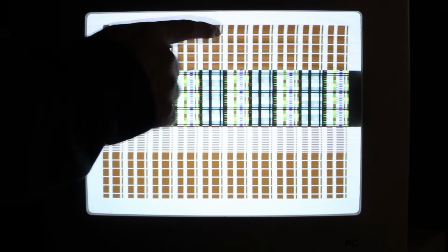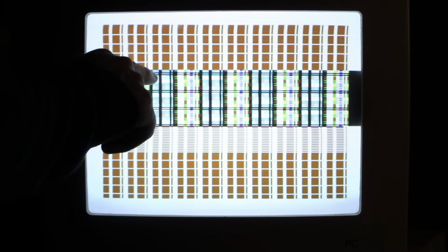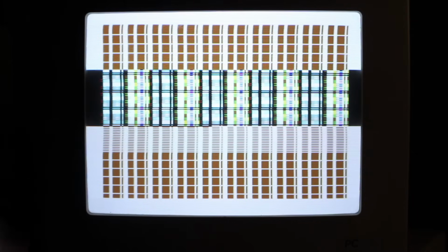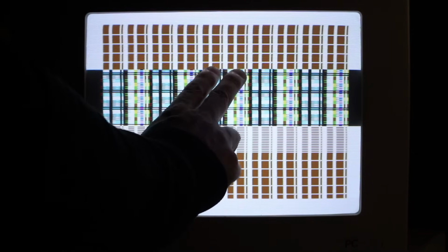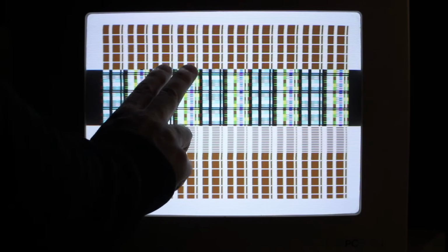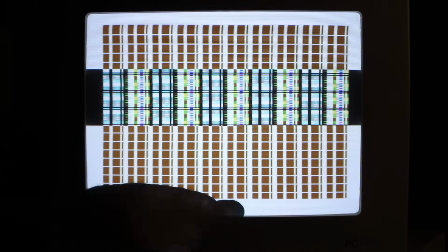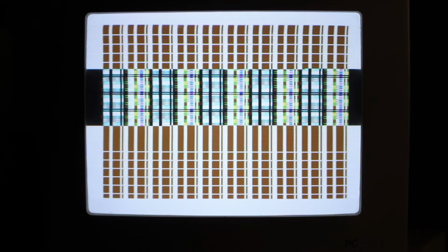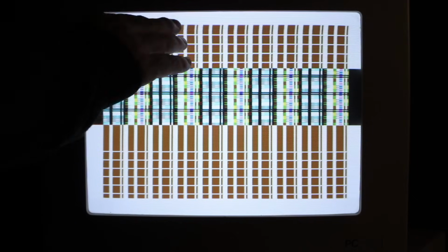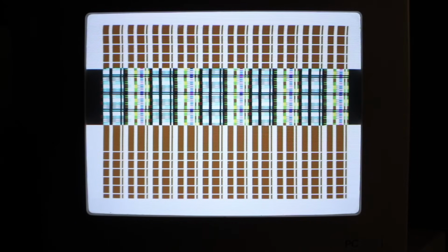So I could actually add an additional register write to change that register value when I'm changing modes, and that would certainly deal with the issue, but then you get a gap between the two modes about the width of a register write, and so that's not really what you want. It'd be alright if it was over here in the border region, but not if it was in the middle of the graphic. And I haven't thought of a nice way of getting around that.